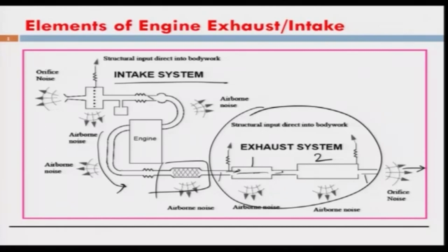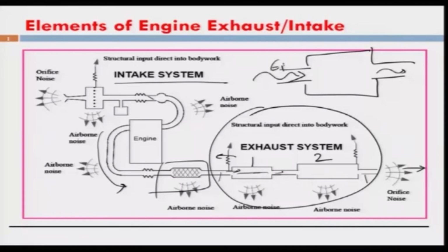And most of the acoustic power is then transmitted upstream, and there is a lot of power that is radiated out. This is called structural acoustic noise or the breakout noise. We are not going to worry about that part, at least in this course. We are just going to focus on this: if you have a muffler like this, if you have a certain element like this, and a certain wave incident here, what is the ratio of the energy incident and the energy transmitted? We are trying to study that, and the log of that.